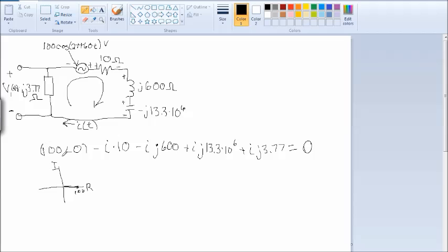So what does that tell us? That tells us there's no component of this voltage source that has an imaginary portion. So there's no J's involved. So in rectangular coordinates, we can just call that 100 volts, because there's no J. In rectangular form you have a complex number.